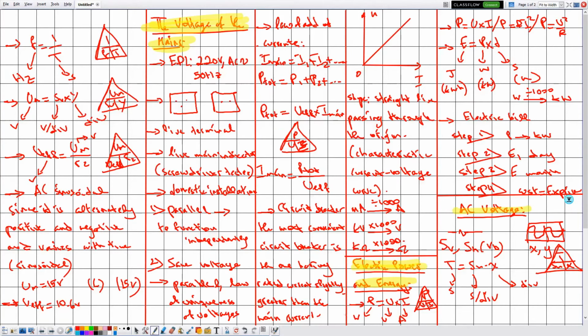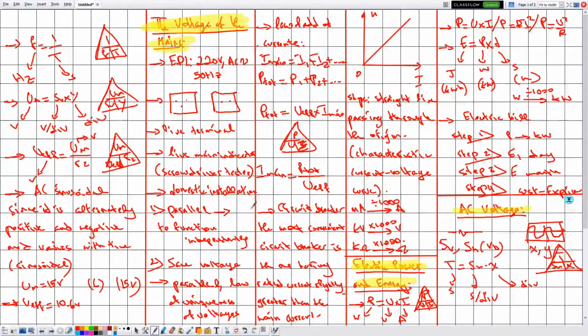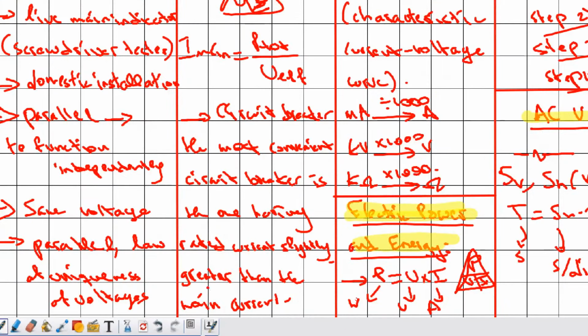So for example, if the main current is 21 amperes, and we have three choices given by 15, 22 amperes and 25 amperes, we're going to choose 22 amperes because it is the closest and the greatest, so it should be greater.